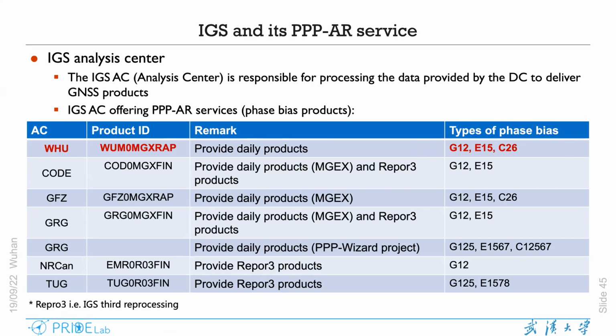Sometimes for some really bad data, if you have not done robust measures to take care of the outliers and cycle slips, then your software cannot do a good job. So that needs attention. That needs to be taken into account before you do a reasonable comparison.